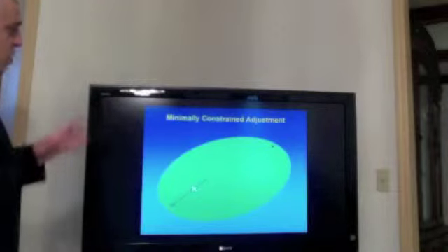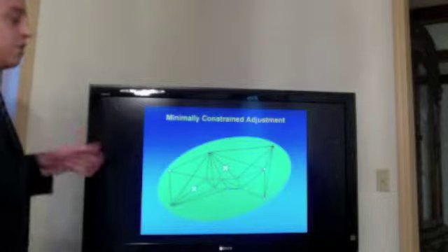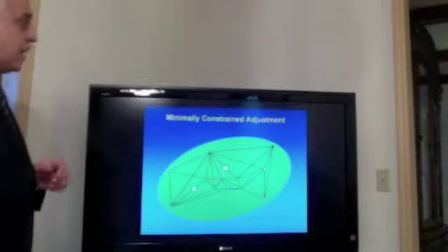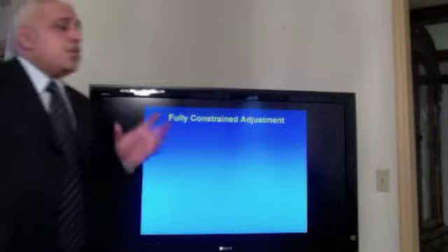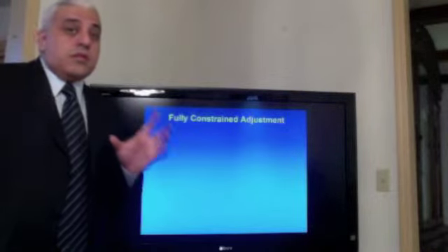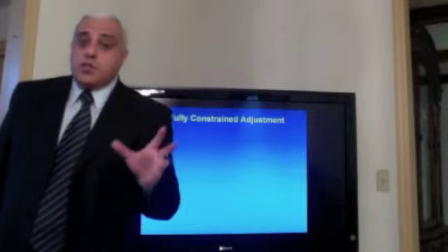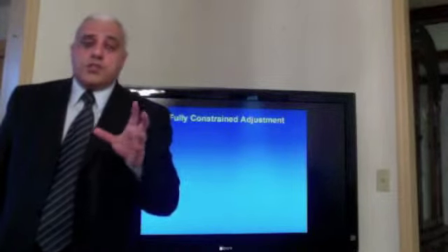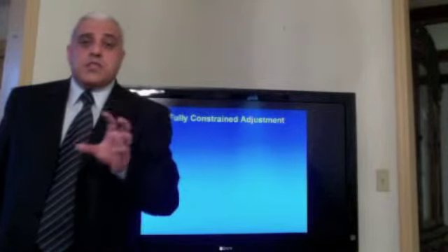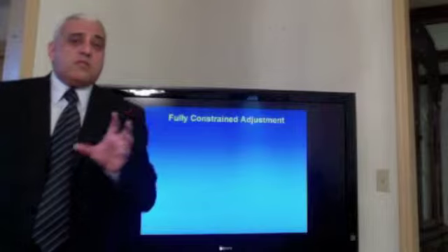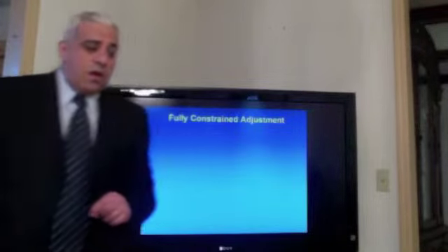And we hold that measurement, and we run the least squares adjustment, and then we judge the statistical result of the chi-square test, which shows us the success evaluation of our error estimate.